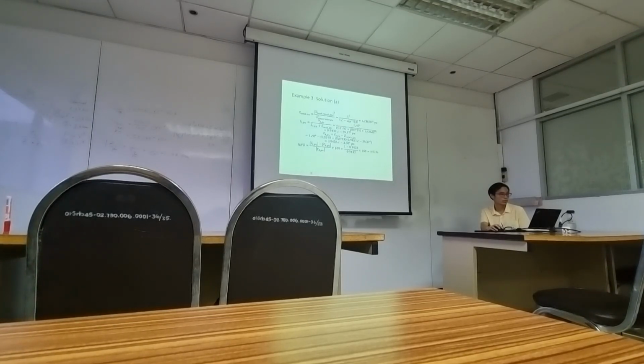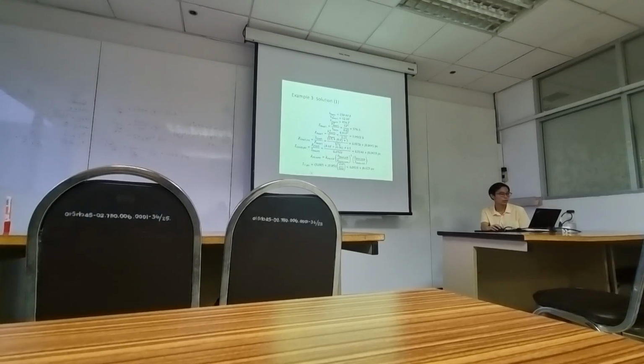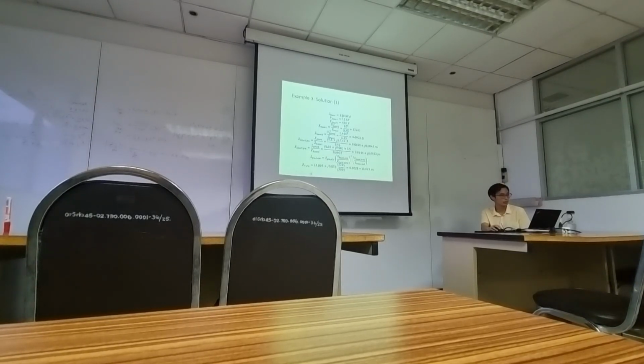So this is 1 per unit. S load is what? 250 kVA. The base is also 250 kVA. See this? So this is also 1 per unit. The power factor is 0.8 lagging, so include the power factor here. So the load impedance is 1 angle 36.87 degrees in per unit.